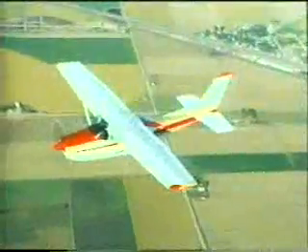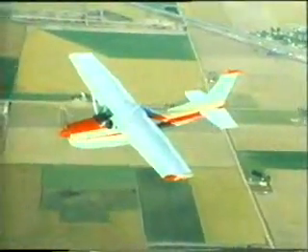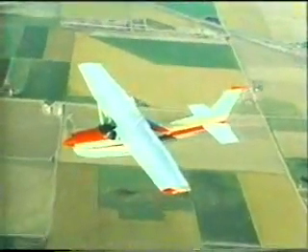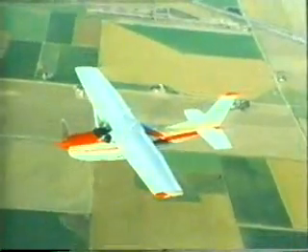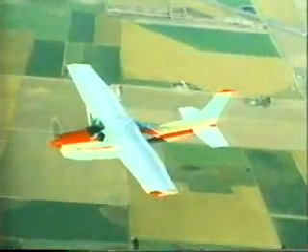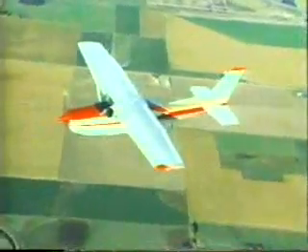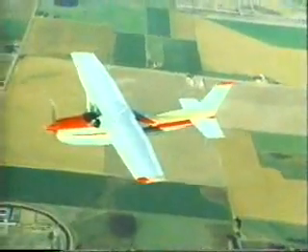As we expand on the formula, lift is shown to be directly proportional to the square of the velocity. For example, if you double the velocity, lift increases fourfold. This means that an airplane flying at 150 knots experiences 4 times the lift as it does when traveling at 75 knots, as long as the other factors, including angle of attack, remain constant.